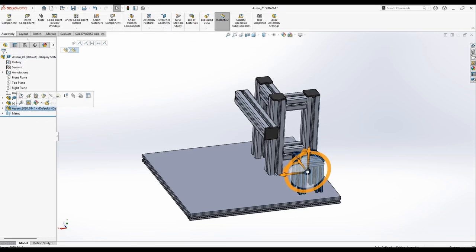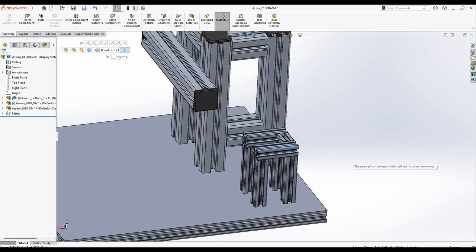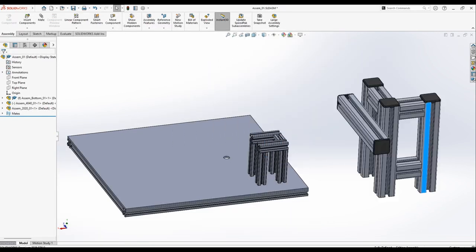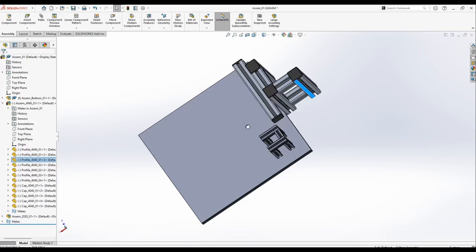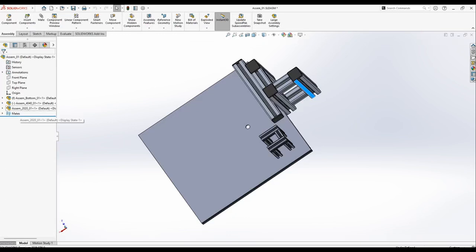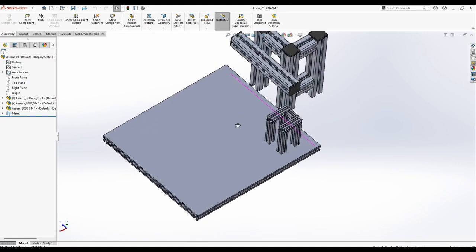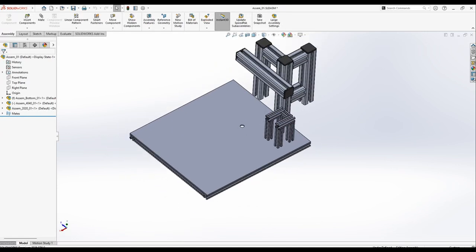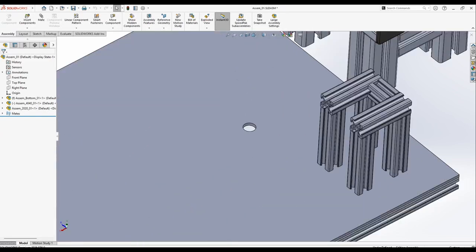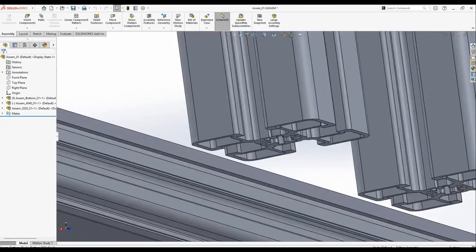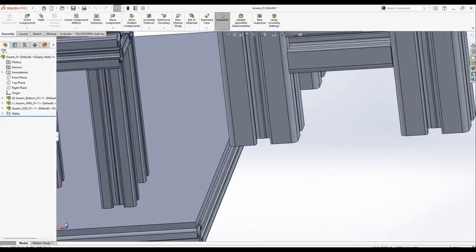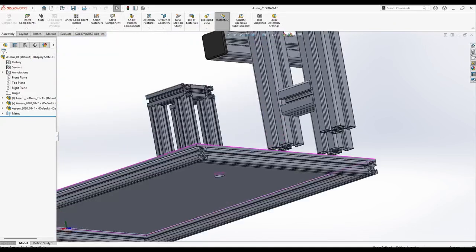This third one also fixes itself fully in the environment. I can't move it, and I check this one, so this I can move. It means not very well positioned, with the minus sign. So I need to position it well. It's wrong. How can I do that? I have the hole here, and this hole was for assembling this part, and I need to position it here.